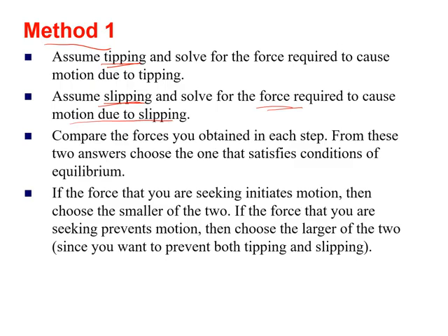Now after that you have to compare the two forces that you find out, first by assuming tipping and then by assuming slipping. If you want to find out whether the force that you are seeking is initiating the motion, then choose the smaller of the two forces. And if the force that you are seeking is to prevent the motion, then choose the larger of the two forces, since you want to prevent both the tipping and slipping conditions. So this is the method that you can follow while solving problems related to tipping or slipping.